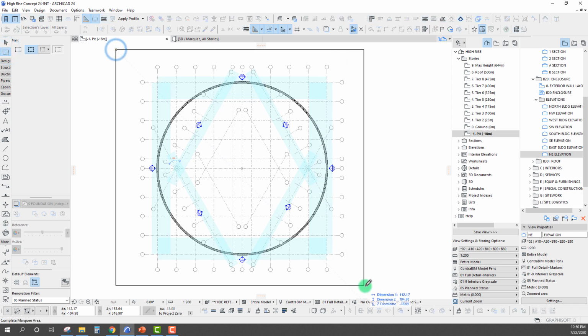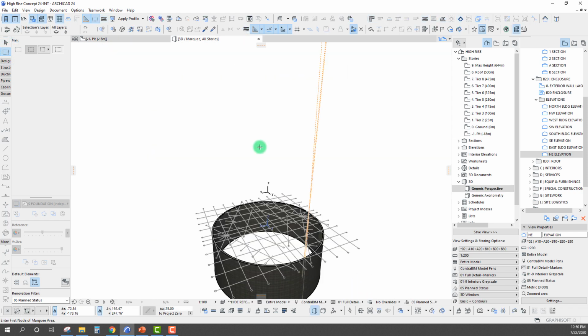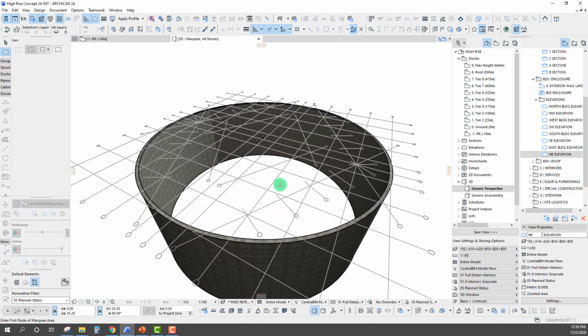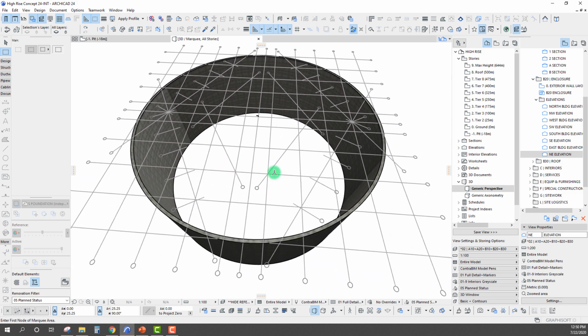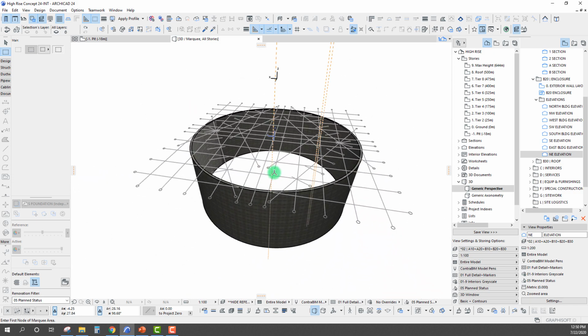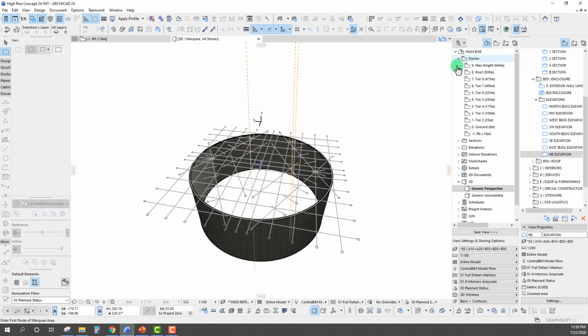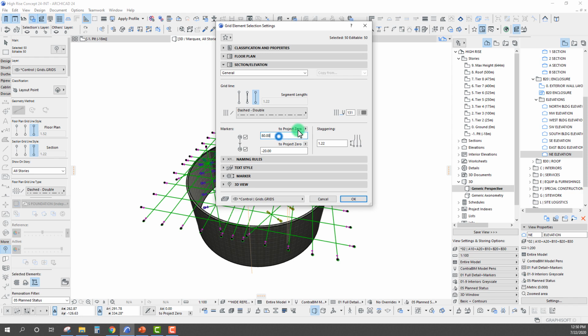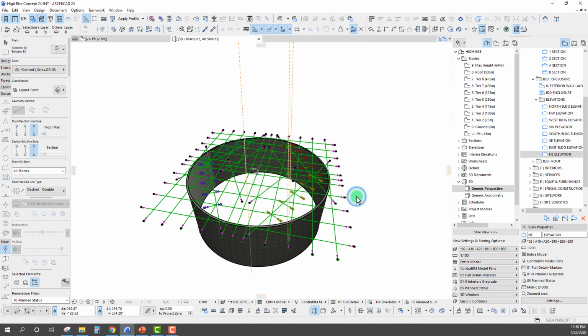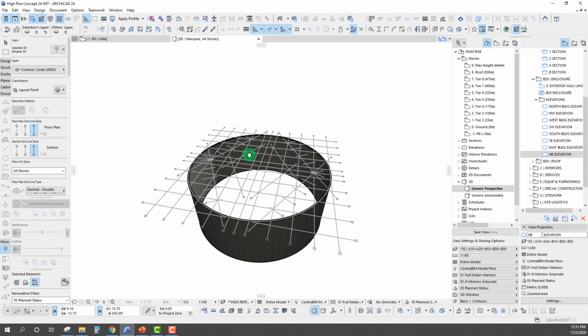Let's take a quick look at all of this here in 3D just to check in to see where we're at. So, all right, there's kind of a spider web of different grids, but that's going to be really useful as we start working through this process. One thing we should probably point out is with these grids, I'm going to select them all, and let's make sure that we have them extended to the right height vertically. So to project 0, we want to be at least 650, and minus 30 is probably good for our depth there. So, okay, got those taken care of real quick.